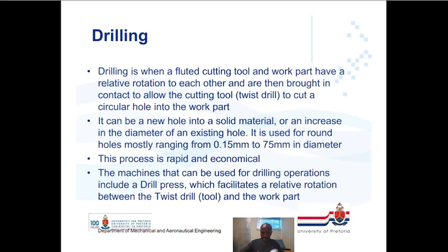With drilling, as I have indicated previously, it has an overlap with boring, but it's a process of making holes, or fabricating or manufacturing holes, into solid components. So that is basically drilling. You can have drilling operated on a circular feature or on almost all the shapes that you can think of. Usually with drilling, you will start a new hole, and with boring, you need to increase an existing hole. So drilling will start your hole.